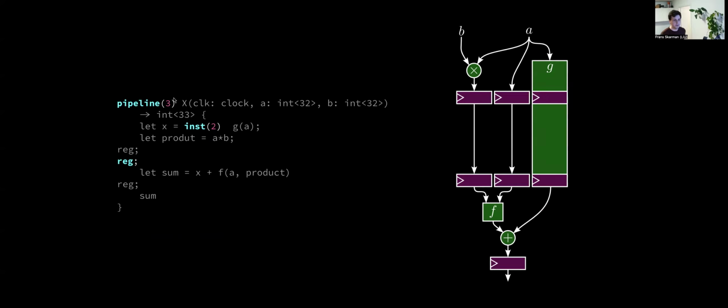And in that way, we purely mechanically change the latency of this inner pipeline G, and the program will still behave as expected, assuming we don't care about specific latency, of course. But hopefully we've instantiated this pipeline either in another pipeline, so latency is taken care of, or somewhere else where latency isn't a problem. And even if it is, this inst2 will still make sure that we check back where we instantiated the pipeline to see, okay, did this affect anything?